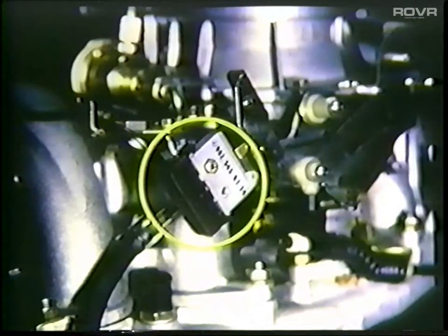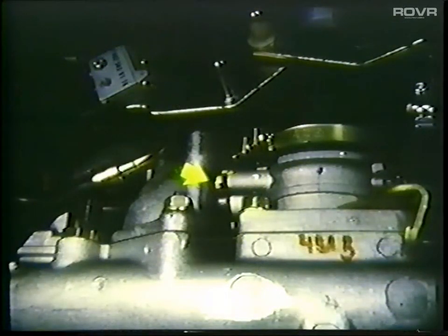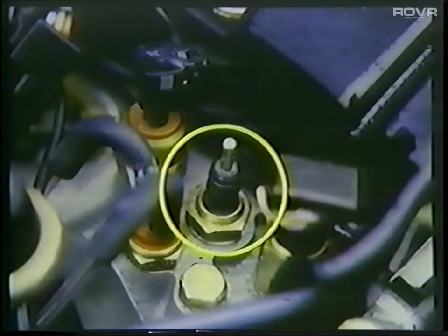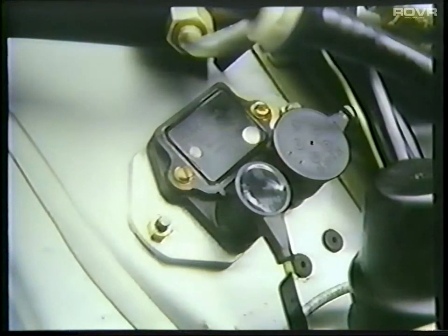Two switches are required to signal the position of the throttle plate. The micro switch signals idle position, and the throttle switch signals wide open throttle. A temperature sensor transmits a resistance dependent on the engine coolant temperature. An engine RPM signal is provided by the ignition module. And the oxygen sensor is utilized to provide information on the air-fuel ratio as indicated by the oxygen content of the exhaust gases.